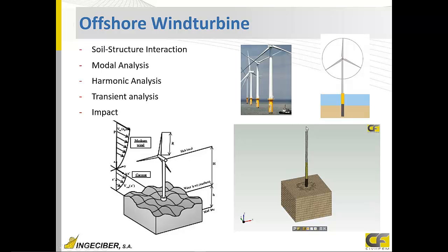So we are going to solve a modal analysis in this model to check the frequencies, a harmonic analysis, forcing it with some forces just to obtain the maximum response, and also a transient analysis with the same sort of loads to analyze in detail the response of the structure. And finally, we will perform an impact of a ship on this pile.